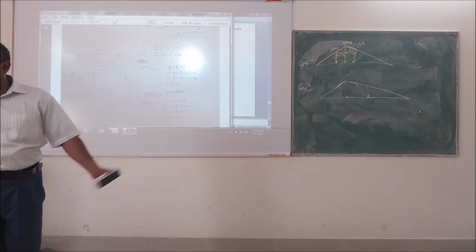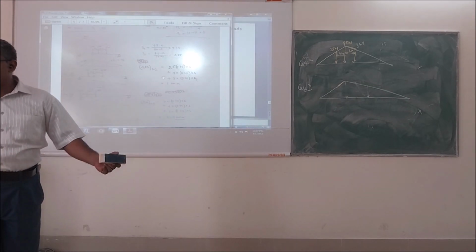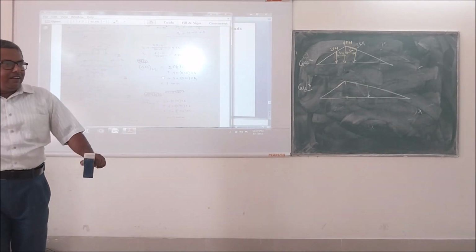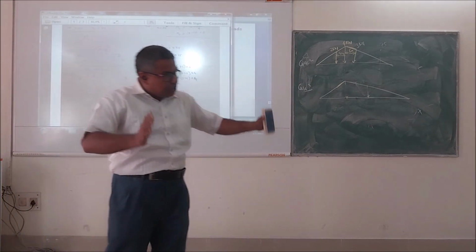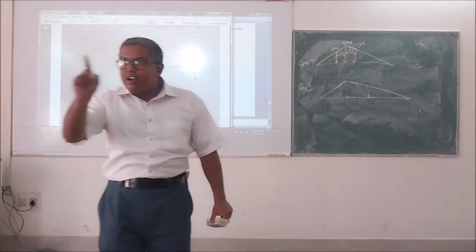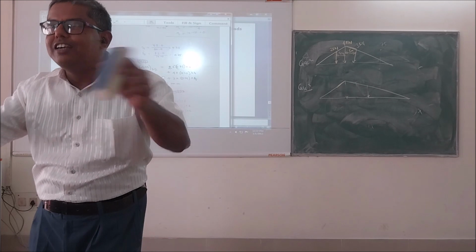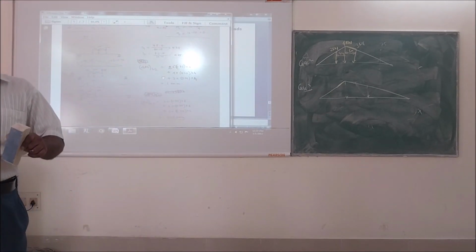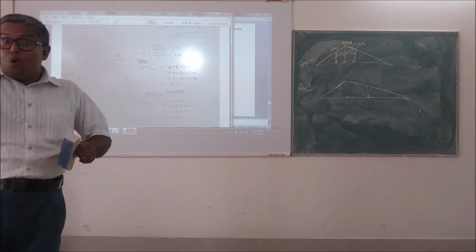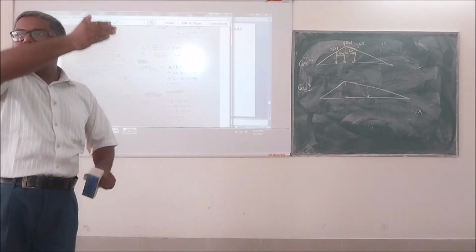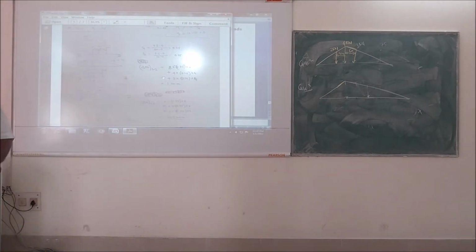Will it be 6 meter or 4 meter? It will be 6. If the back wheel is moving by 6 meter, the front wheel needs to move by 6. So it is not dependent on the separation distance. Rather, it is the movement of the load and how you position the load on the maximum ordinate.